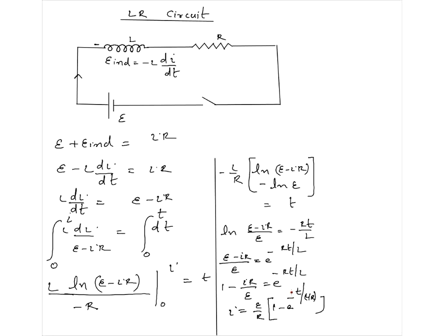Now this is what we would have expected in current electricity, resistance, battery, E by R. But this is happening at t equal to infinite. That's due to the inductor. Yes, practically infinite doesn't mean infinite time. Practically infinite means quite small actually for LR circuit. But nevertheless, delay is there. At t equal to 0, it is not E by R.